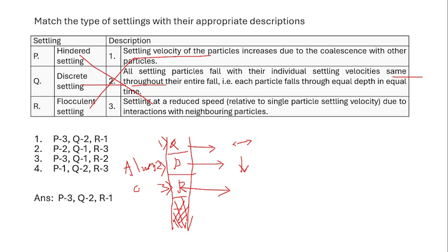Now after the completion of the reaction, the flocs will be formed. So once the flocs are formed, these are larger in size, right? So these particles will settle down very fast. So again the settling speed increases. So in the compaction zone, since it is the extreme depth of this region, the settling velocity will increase further. So this is what we have studied.